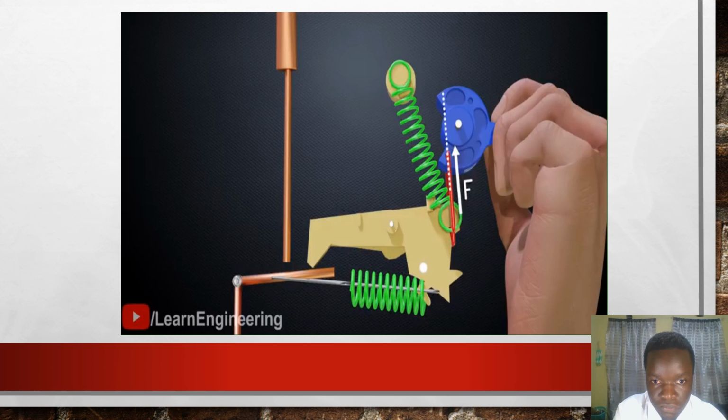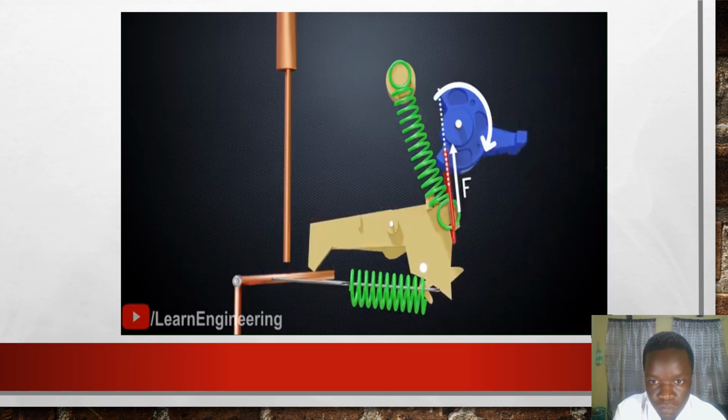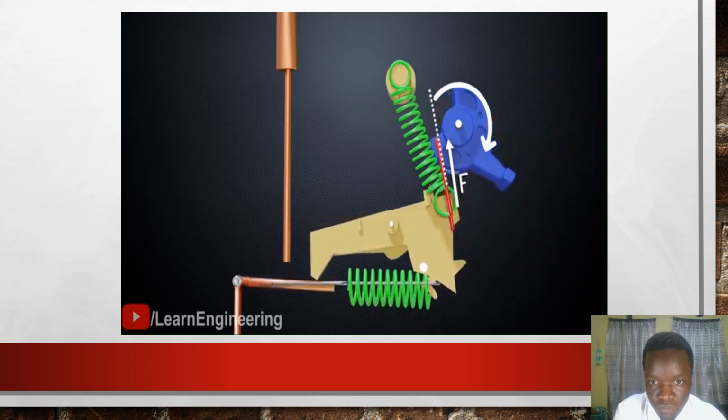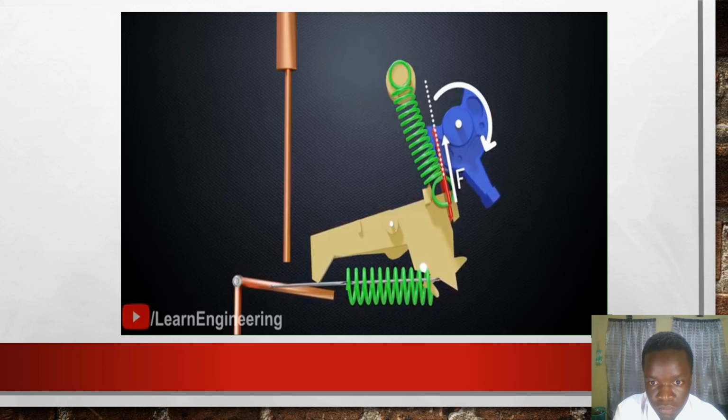As you can see, the rectangular ring is initially at a negative offset to the center of the lever. The torque produced by the force acting on the rectangular ring will be in the clockwise direction. If you release the lever in this position, this clockwise torque will bring the lever back to its initial position.